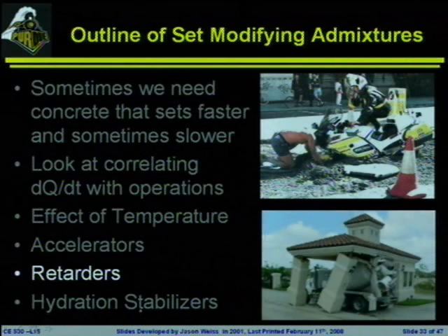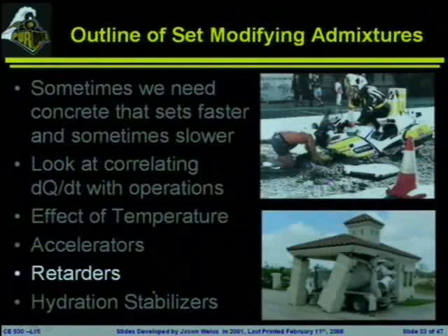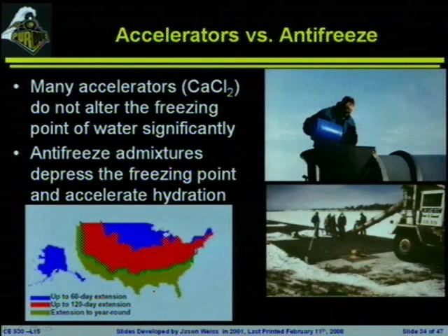Retarders, we'll go very quickly through some of the retarders that may be out there. Well, I guess before we jump into retarders, we're going to talk about accelerators and antifreeze. One of the things that I do want to point out here is there is a series of materials that are not necessarily accelerators, but they are used in cold weather climates. The basic idea is these would be used to depress the freezing point of the system while accelerating hydration.